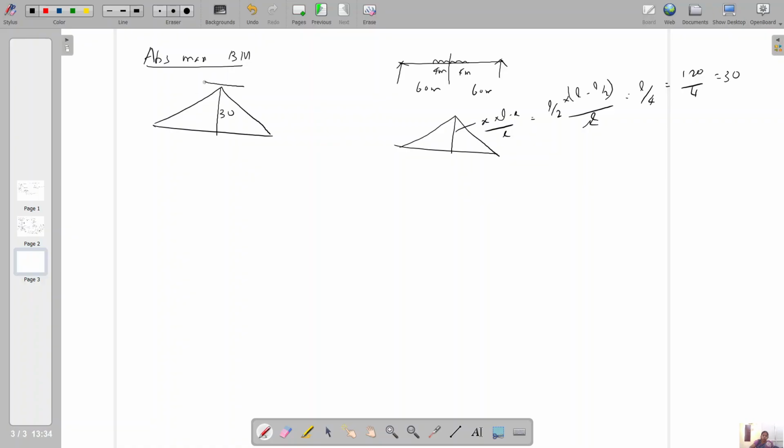You superimpose the load in a symmetrical way because of absolute value. Okay, the span is 4 meter, 4 meter. We need this ordinate O, the same value here also. How can we calculate O? The total span here is 80. If you deduct 4, you will get 76. So 30 is the ordinate for 80. What is the value for 76? So 30 into 76 by 80, which is 28.5. Because of the symmetry, both sides equal 28.5.